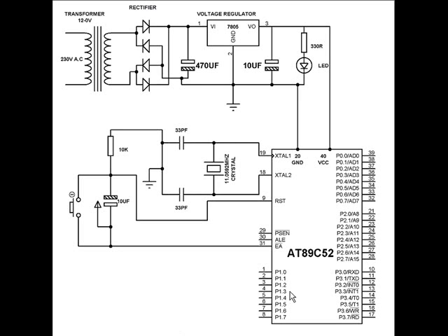For every microcontroller, whether it is 89C51, C52, or 89C2051, these are all 40 pin ICs, those are 20 pin ICs, but in all the cases we need to have certain standard connections. Standard connections are at least the power supply section, which has been separately discussed, where we